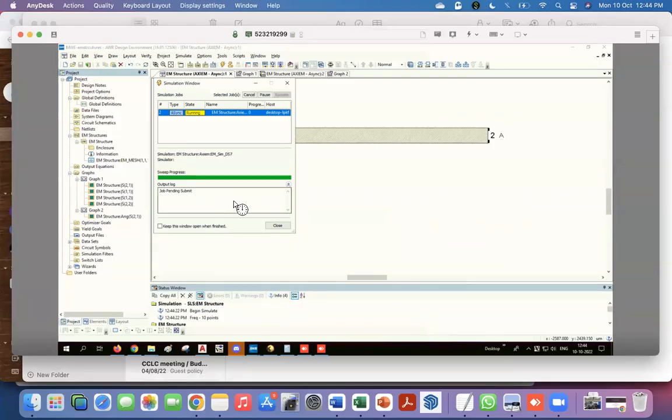So just to summarize the essential things you have to keep in mind about these finite element simulations: if you're not careful about setting it up, and there are other subtleties which we'll discuss later about the ground references, but for most standard things, it's not a problem. And you have to keep in mind these kind of numerical errors which can creep up. You cannot trust them blindly. Okay? You need to have some idea of the physical system you are actually trying to simulate. You know it from knowing about the structures, so that you can then take the results and interpret them correctly.